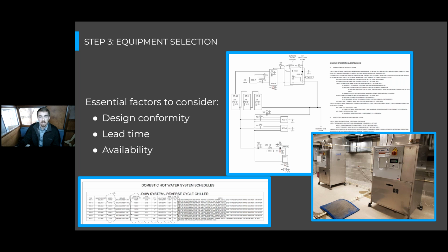There's a really wide variance in the lead times on these heat pumps right now, especially with a pairing of the lead time issues for a lot of the components they have to use, as well as the really quickly peaking interest in heat pump water heaters based off their really high efficiency. So you want to check with the manufacturer, their rep, on the lead time of this equipment and how that fits into your project.